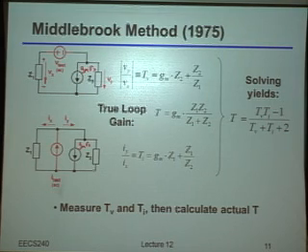The next thing I do is reclose the feedback loop. So I'll connect the feedback side back to the output of the amplifier. But now let me apply a current source, which you can almost think of conceptually as being in parallel with that particular connection. And let me again measure another transfer function, which in this case will be the ratio of the current flowing into the amplifier versus the current flowing back through the input network. So that's just going to be these two transfer functions. The first I'm going to call TV. The second I'm going to call TI.